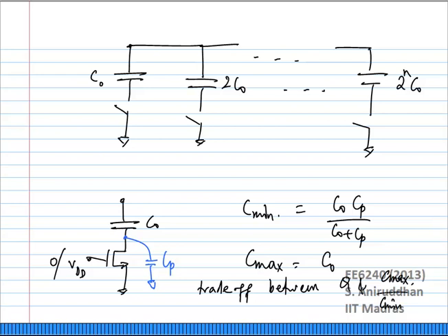The minute you add these kinds of binary weighted capacitors, you need to make sure that this fine-tune range of the VCO covers every possible frequency over the range of frequencies that you want. If you want the VCO to tune, let us say between 2.3 to 2.6 gigahertz, okay? Let us say if your KVCO is 30 megahertz per volt, right? How many steps do you need? You need 10 steps, first of all.